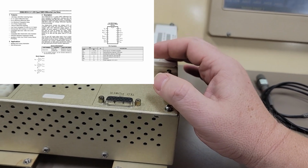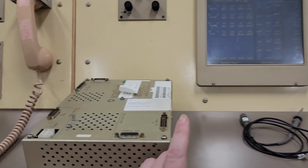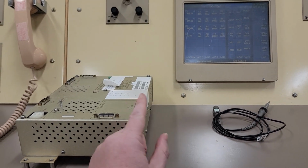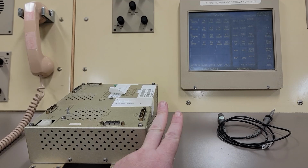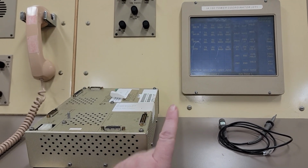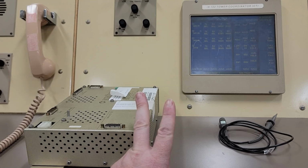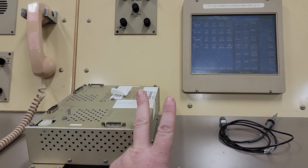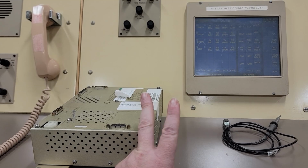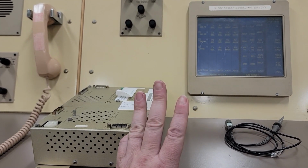There's several pins, and what they do is they take that RGB, red, green, and blue, and say I'm just looking at the red at one input on this IC. It's going to provide me two outputs based off that one input. One output is going to be at the same amplitude as the input, and you could say probably the same phase, even though that's not really correct. The other one's going to be an inverted output.